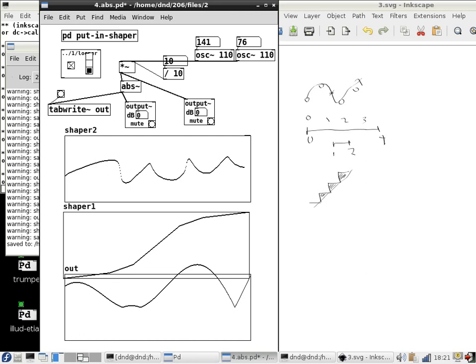One thing that I mean to tell you, as soon as we need it, we haven't really hit a bad foldover situation yet, so I haven't had to do something like this, but one can always make a sub-patch and run the sub-patch at some huge sample rate, and then filter and then downsample as a way of controlling foldover. And then you can get closer to the quality of an analog thing than you would have been able to